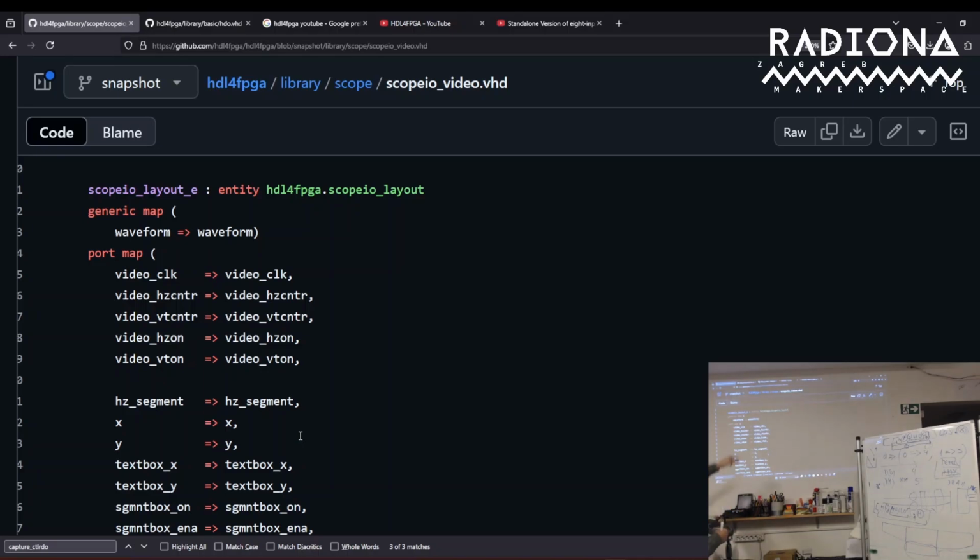So getting first the waveform string and then passing it should be faster. If you try this in GHDL, you won't feel the difference. But for the synthesis tools, I don't know what it's doing inside, but there is a difference in time, and it's your time.